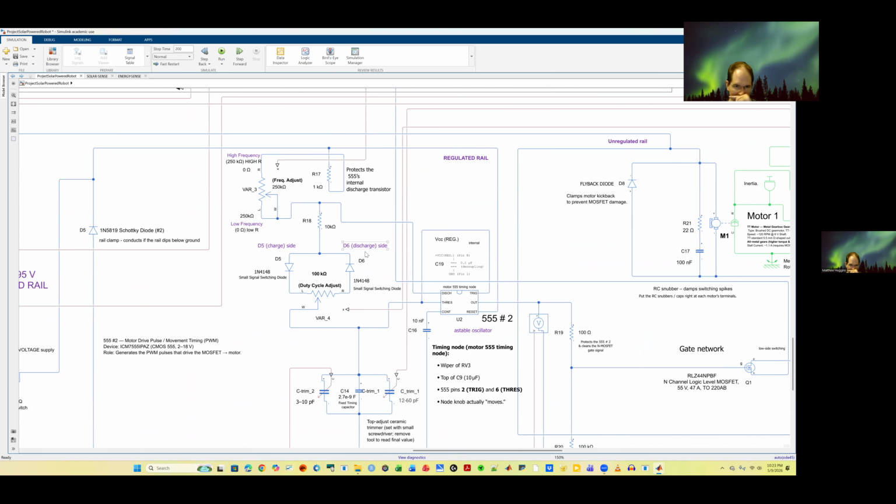And the way this works is, as you vary the resistance, the length of time that the capacitors down here discharge corresponds to the length of resistance that it has to go through. So if you want a shorter time period, you want less resistance. If you have more resistance, it's going to take a longer time constant.